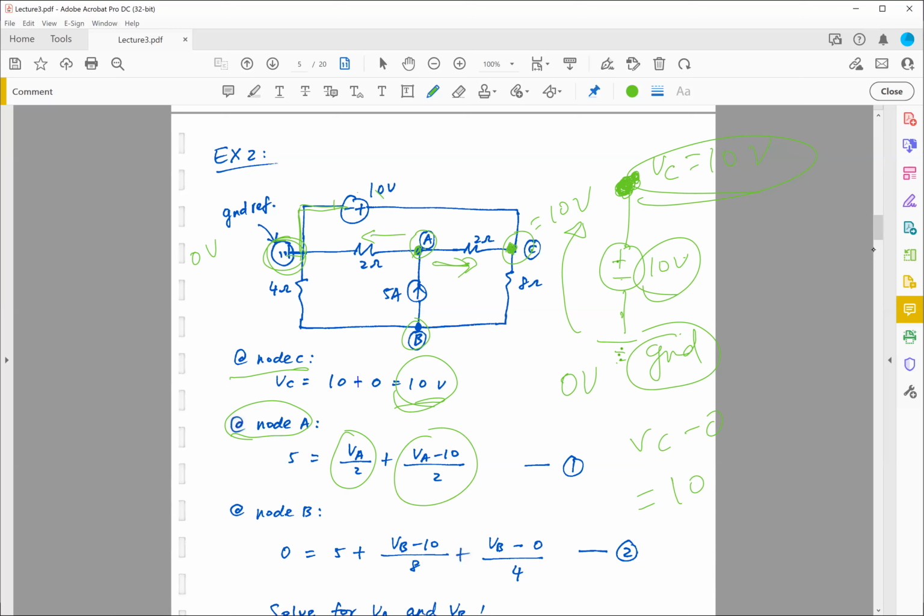This term over here. And remember, KCL says the sum of the current entering the node has to be equal to the sum of the current leaving the node. So over here, I spot this current entering the node. This 5 mA is flowing into node VA. So instead of saying plus minus 5, I'm just going to put it on the other side of the equal sign. This 5 indicates the current flowing in, so entering the node, and this has to be equal to the current leaving the node, which is taken care of by this term and this term, which is this current and this current.